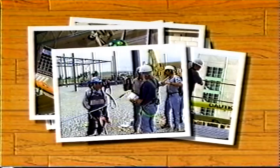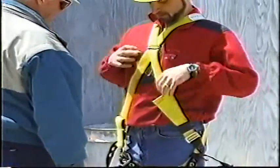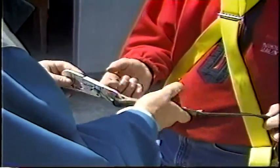Whatever the solution, you must know how to use the equipment correctly and maintain it carefully. Employers must ensure that workers are trained in fall protection and that fall hazards are controlled or eliminated. Workers must use fall protection equipment whenever it's required and report any defects or hazards. In the event of a fall, you must know your employer's written rescue plan. The key is prevention. Prevent falls from happening in the first place.